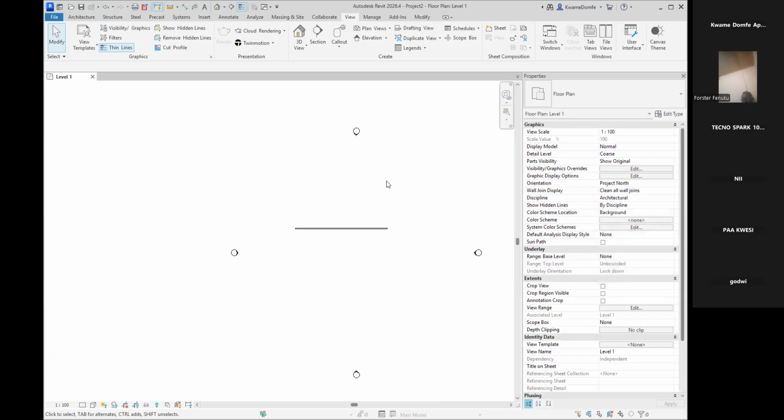If you select a wall, a window, a text, a title block, a line, dimension, anything you select, 2-dimensional or 3-dimensional, you can edit it in the what? Properties palette. If it is a schedule, you can edit it in the properties palette. If it's a legend, anything about it, you must edit them in the properties palette because that is how Revit is designed. If you don't edit stuff using the properties palette, then it means you are not doing parametric modeling properly.